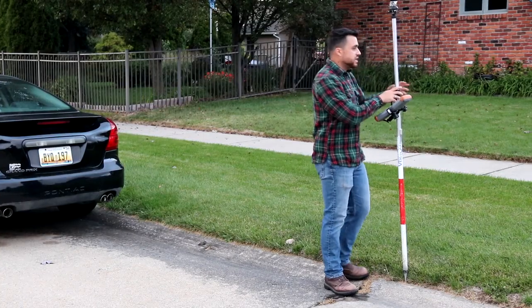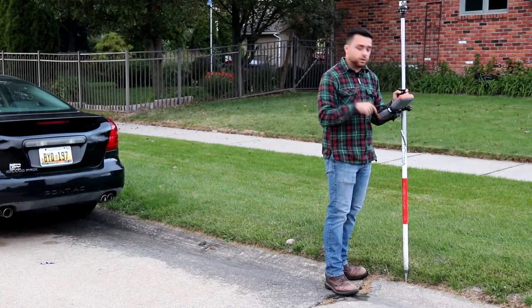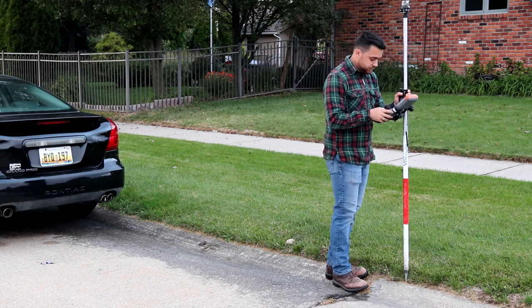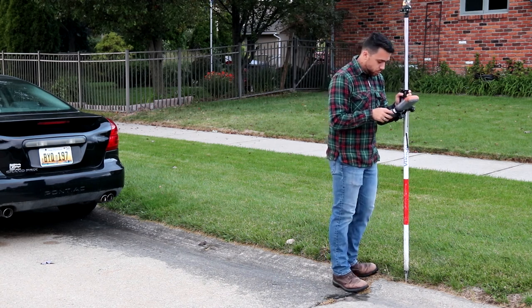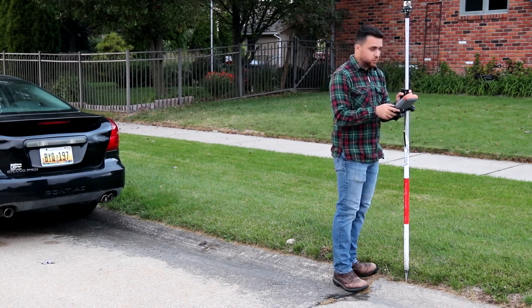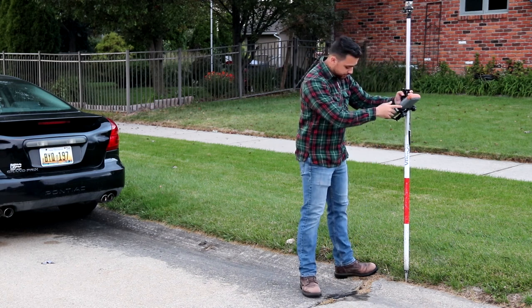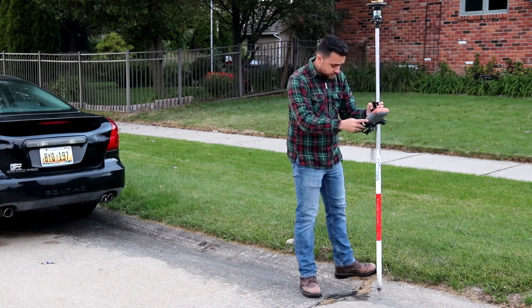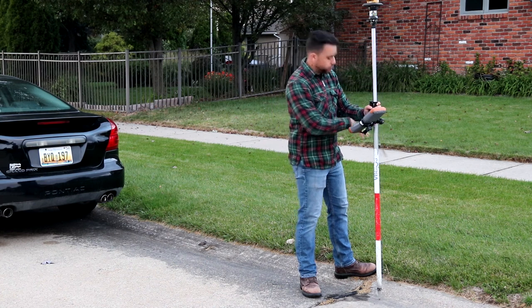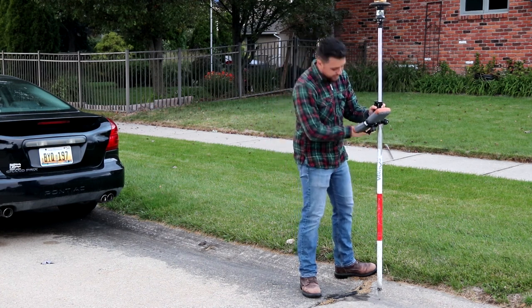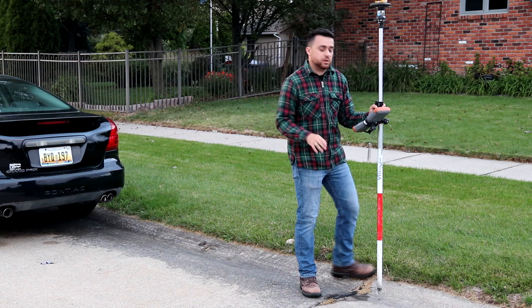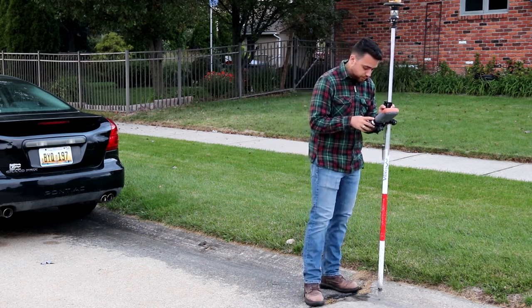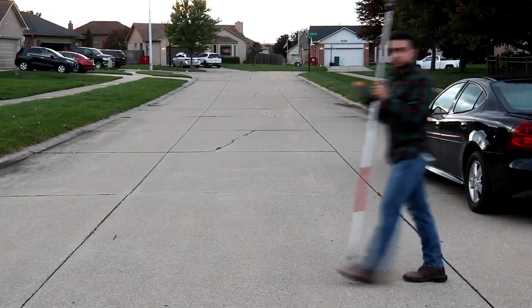Now after recording the sidewalk shots, I'm going to go ahead and record our curb shot. This is going to just be curb 1. Okay, after taking the curb shot, I will move the instrument down, and this is our gutter. We want to take this right next to the curb shot, but at a different elevation since it's sloping down. So this will be gutter 1.